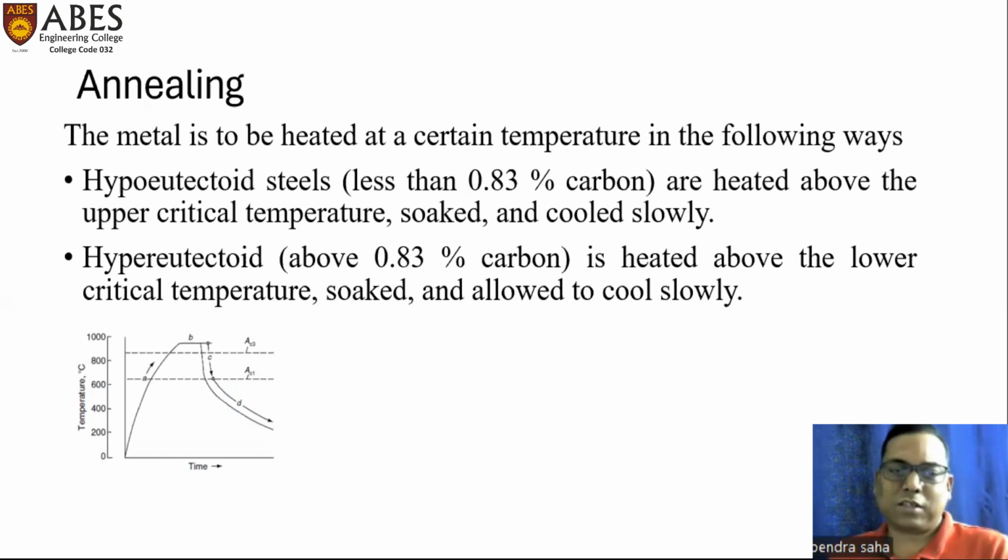In this figure, we can easily see that the temperature is near about 800 plus degrees centigrade, and after that there is a soaking time, and after that it is dropped down to room temperature. So annealing is applied, using the furnace cooling process.